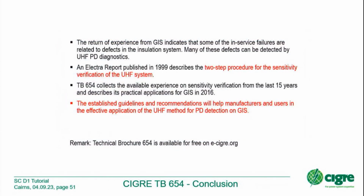And here the conclusion. The return of experience, and I think this is also valid today, shows that we have some defects, we have some failures and outages, and many of these defects can be detected by partial discharge in the factory, during on-site testing with higher test voltages, as well as in service. And if we can detect these partial discharges, we can take some action, repair, etc., cleaning of the GIS. This will increase the reliability of GIS.